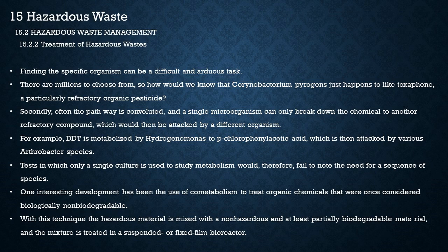One interesting development has been the use of co-metabolism to treat organic chemicals that were once considered biologically non-biodegradable. With this technique, the hazardous material is mixed with a non-hazardous and at least partially biodegradable material, and the mixture is treated in a suspended or fixed film bioreactor.